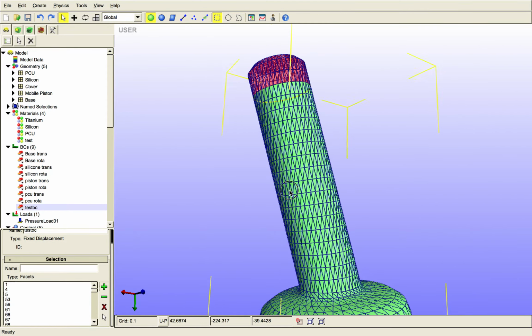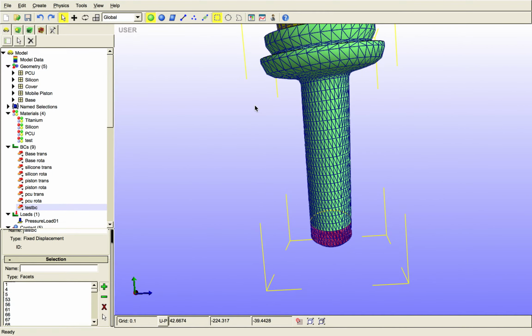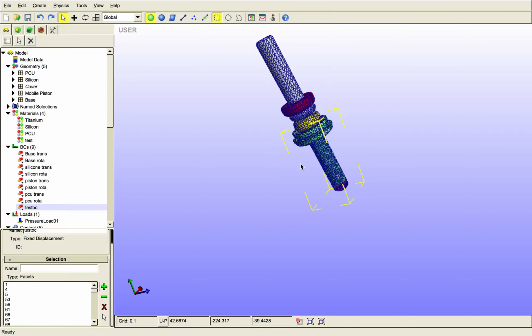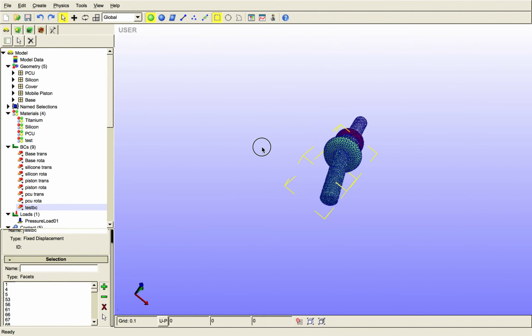If you want to add the same boundary conditions for two different parts of the model, you have to be aware that you have to separate them, because we have selected this object, and then for these elements, this boundary condition, you can't over here change object and go for a boundary condition again. It's not possible. You have to create another one, and as always, make sure you unselected any elements.